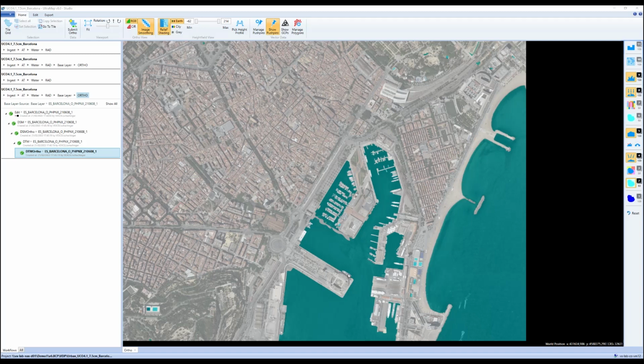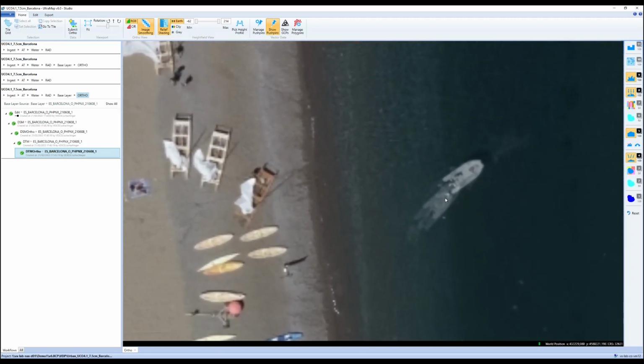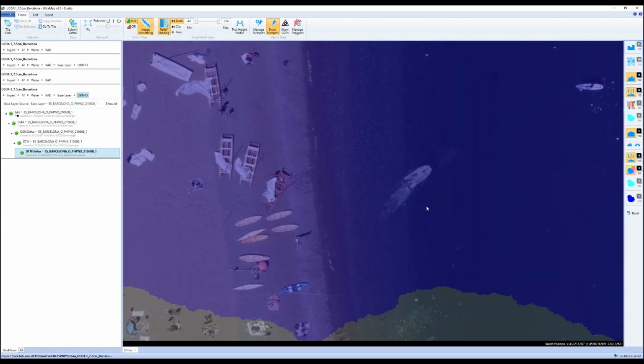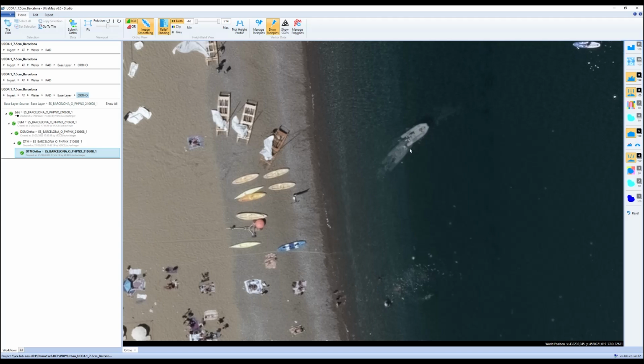The blending helps to improve the seam lines on the water, but it can also create some new challenges. So here, for example, we see a boat which is near to a seam line. So the seam line is just here, and that boat is within the corridor where blending is applied, and therefore the boat is textured in this orthomosaic from two images. Therefore we see there a double structure. This issue can be handled by modifying the blending mask for this particular region here.